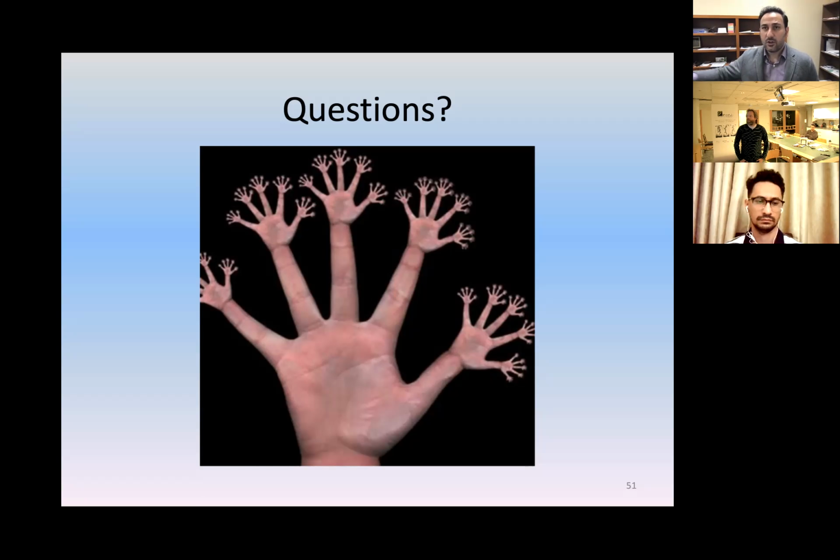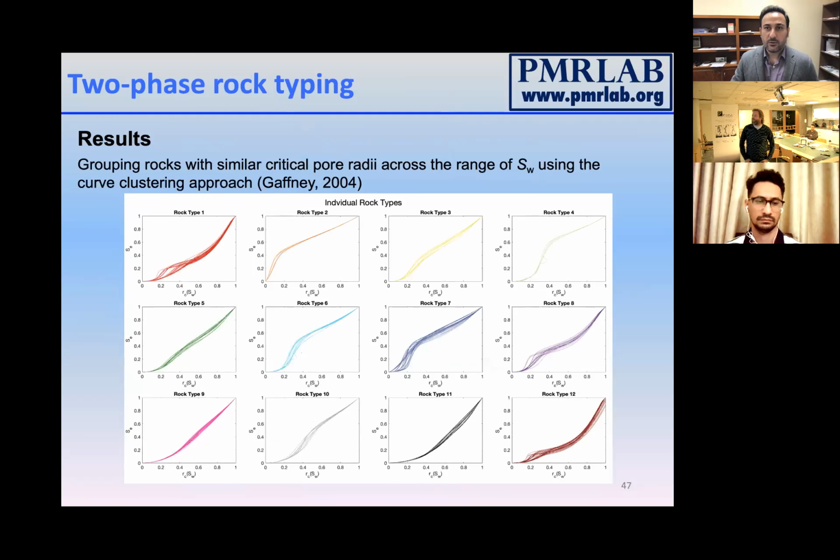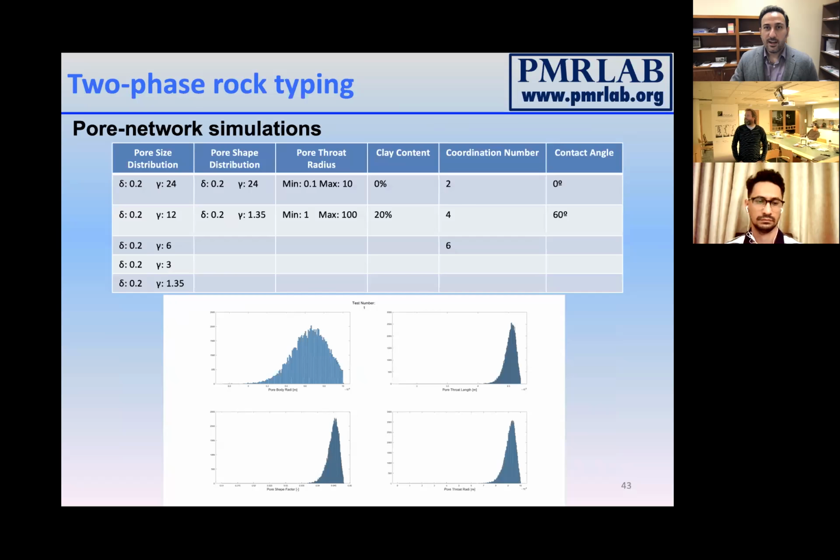So we used two different contact angles. We couldn't actually go far beyond two different values. Right now, we have 240 simulations, and each simulation was actually iterated 100 times. So you can easily see that they are computationally really demanding. If we wanted to include more contact angle values, that would be possible, but it required more time and more computations, so we decided to cut at two different values, 0 and 60 degrees. But definitely if you include more, there is a chance that you get different results.